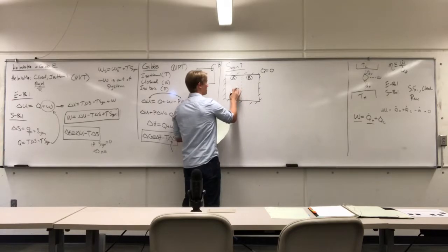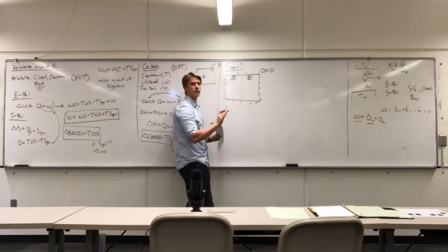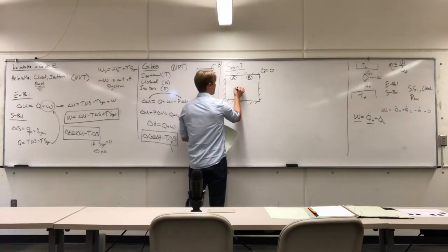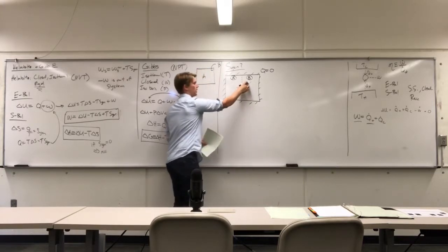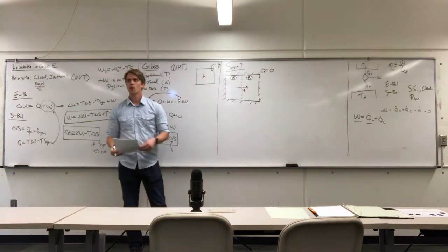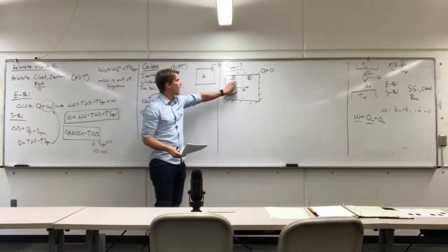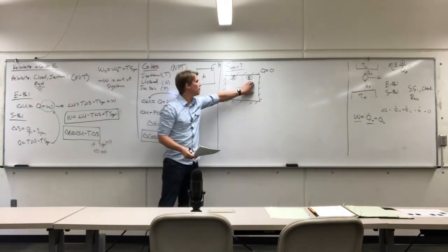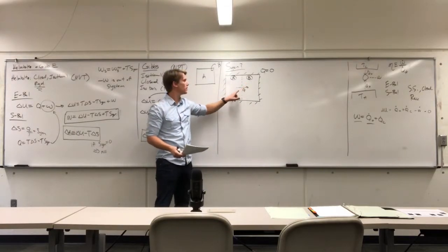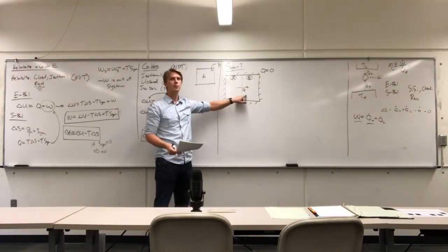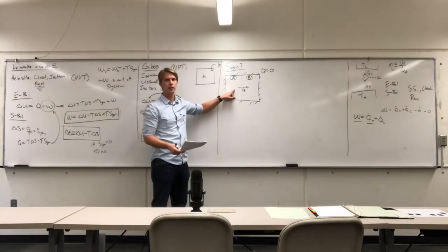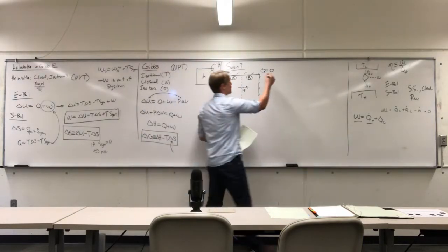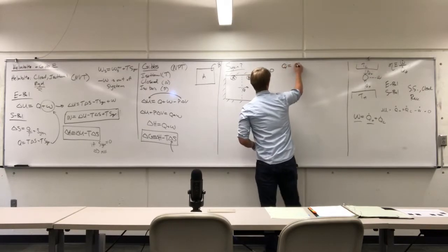So in this case, the difference between A and B is that they're at different temperatures. I'm going to define heat as going from chamber A to chamber B. One additional assumption: chamber A is well mixed and chamber B is well mixed. What that means is that the rate of heat transfer between them is much, much slower than the rate of heat transfer internally.